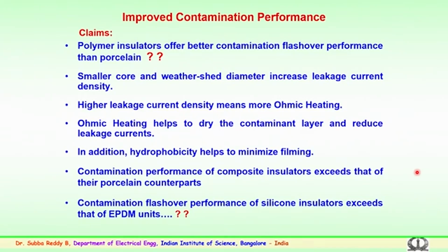These insulators being of recent origin, the field data for longer time performance is not yet available. So, we have to see the performance over a period of time and then conclude that polymer insulators can offer better performance for a very long period of time. Yes, for short term they are performing well and giving better contamination flashover performance in comparison to porcelain or glass type of insulators.